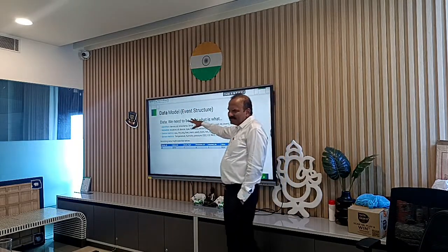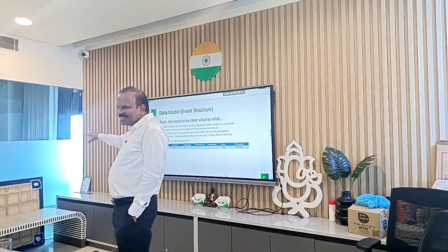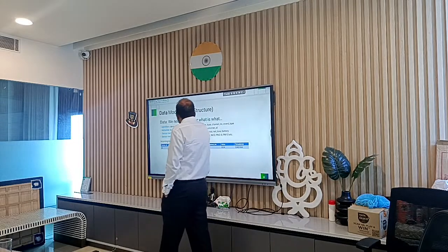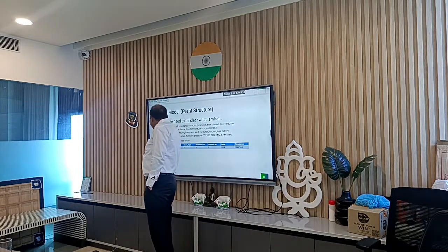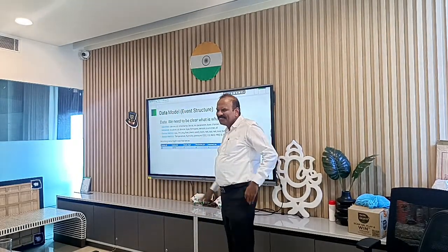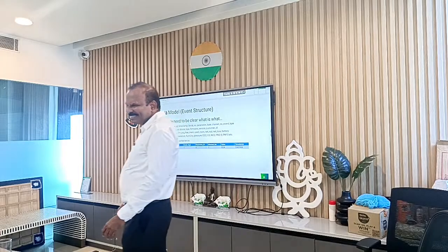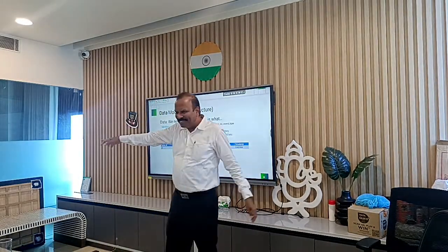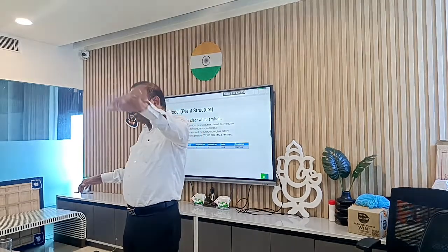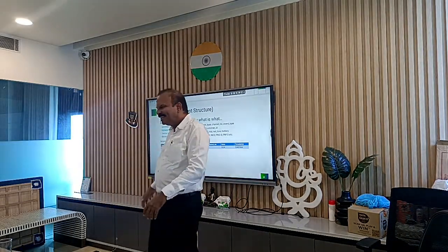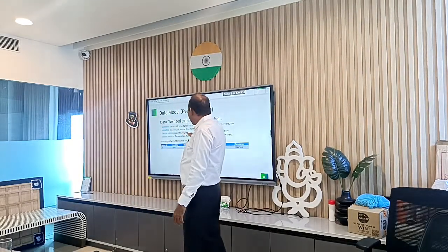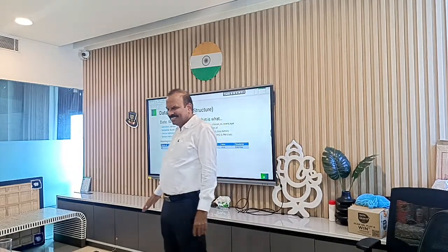So this is the base for any IoT. Of course, when I want to transport this event, I can have 2 bytes of header and 1 or 2 bytes of footer, saying that this is a packet. Because in this, everything is variable, 0 to F, all possible combinations. The header or footer, AA55 or something, or a bracket, whatever you put, indicates that the packet started. Even if you start in the middle, at least it will identify the next packet.